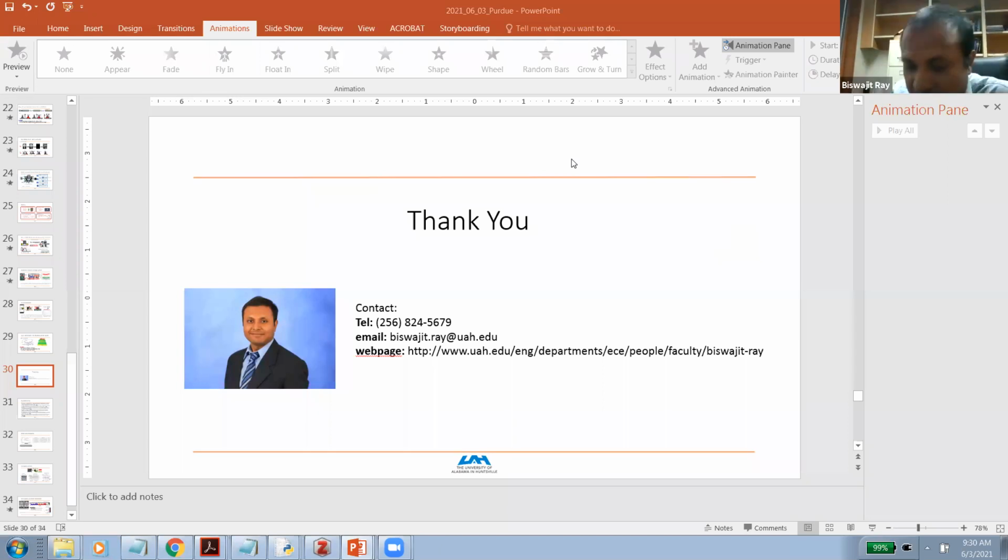Not really. This is an important question you raised, because when you have to reserve a block, for example, for watermarking, a flash memory chip comes with thousands of blocks, minimum thousands, and there are a lot of extra reserved blocks as well. So a manufacturer can use one of these blocks just for watermarking, say manufacturing related information. That is, it is a valid chip. It is not a foundry rejected chip. This is the year it is produced. This is the company that produced it.